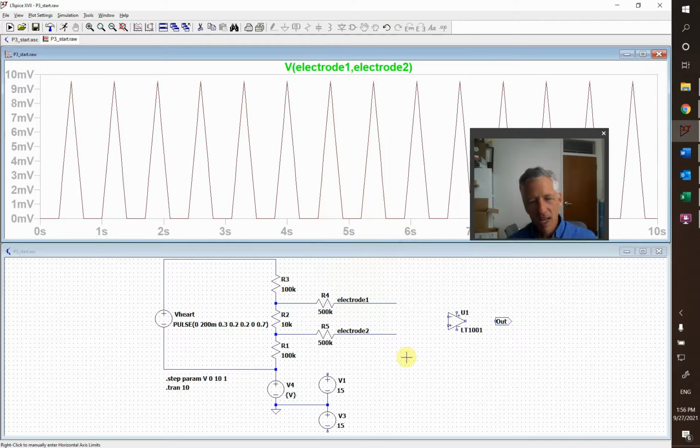Now, in order for this to be a good design, we have to make sure that the design is independent of any of these resistors. So if these resistors go down by a factor of 2, we want a negligible variation, meaning less than 10% variation in the output over here, using whatever op-amp configuration we want to use. So that is the basic design, and don't change the name of this voltage, the name of this voltage, or the name of this node right here when you do this design.